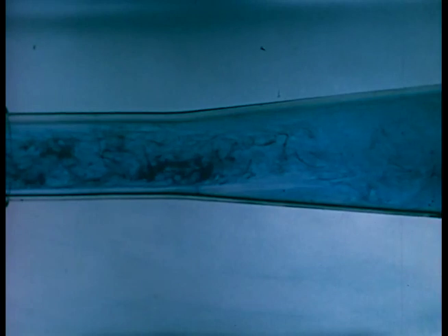Boundary layers do not always remain attached to the surfaces on which they are generated. When the pressure rises in the flow direction, fluid particles near the wall, having already consumed energy to overcome skin friction, do not have additional energy to overcome the pressure rise and to continue their motion. By leaving the wall, however, most particles do manage to keep moving. The boundary layer is then said to be separated.